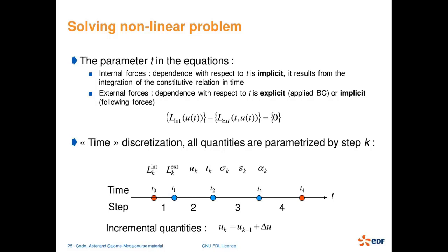Now, in solving a nonlinear problem, what is the basic strategy? Let us see that. We express everything as a function of that pseudo time t. Therefore, my deformations are functions of t, and also the external loads are functions of t, and the internal load as well is a function of t and a function of the deformation, of course, because it is a nonlinear material, and that deformation again is a function of time, as I told you.